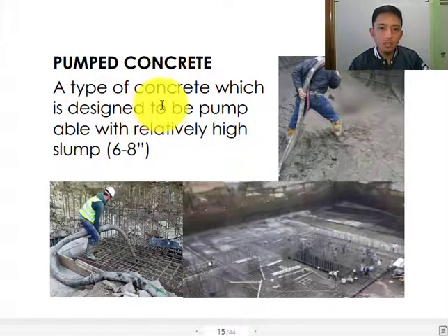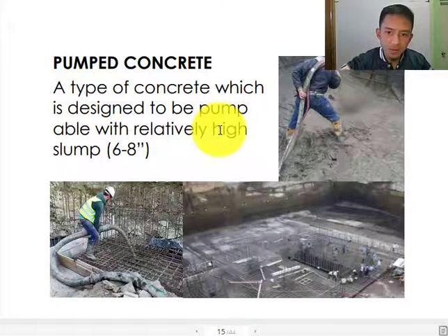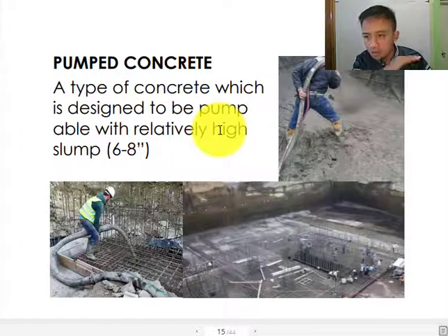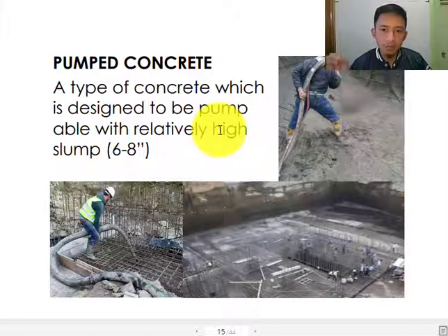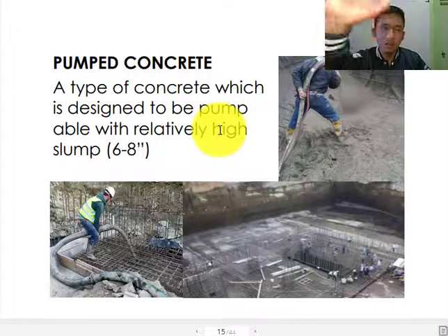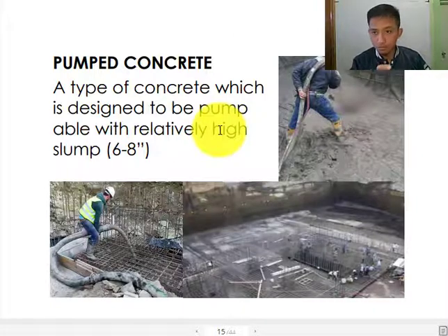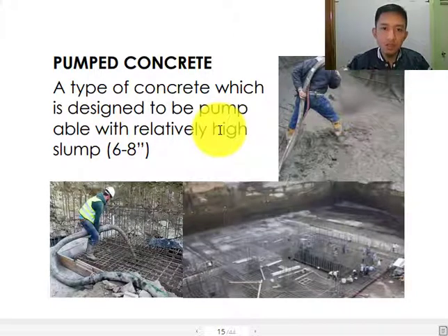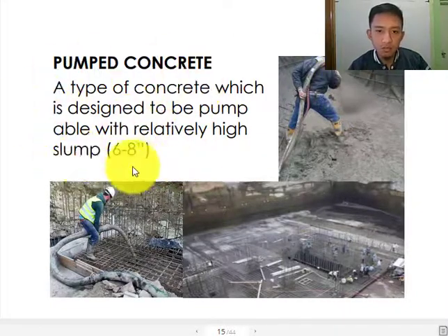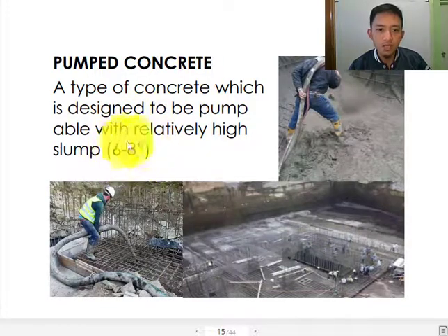Why? Because a pumped concrete needs to be workable and consistent enough, able to flow, for that to be pumped. Just imagine a concrete mix with less water in it, it is hard for that to be mixed and to flow. It is less consistent. Then you're going to pump that one. Of course, the pressure will be exerted by the pump to pump the concrete mix, so that needs to be on high consistency. If there's high consistency, then that should be having a big slump. Easy to flow.